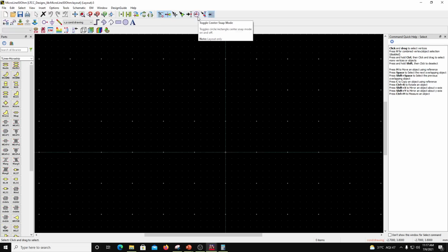Now these are the snap grid options. In drawing, when you move the mouse, it moves freely. But once you start drawing, the mouse will be attracted to one of these smaller dots. This is called snap to grid. When you try to place a point for drawing, it will automatically attach to one of the dots on the grid.